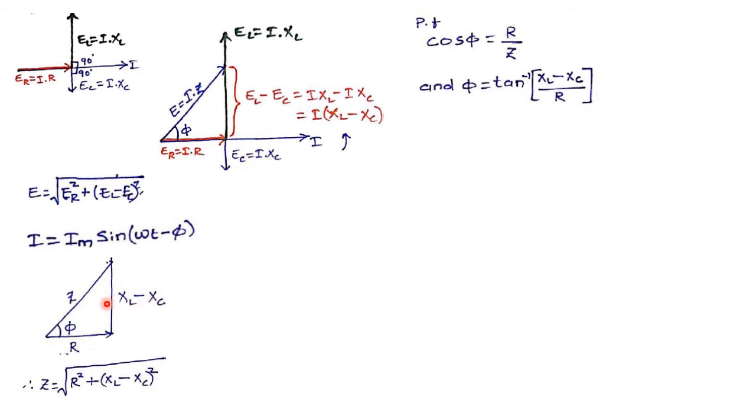So the effective reactance of the circuit is now XL minus XC. There is presence of inductive reactance, there is presence of capacitive reactance in the circuit now, but since both are existing simultaneously and XL is greater than XC, that is the inductive reactance is more effective or more prominent than the capacitive reactance.